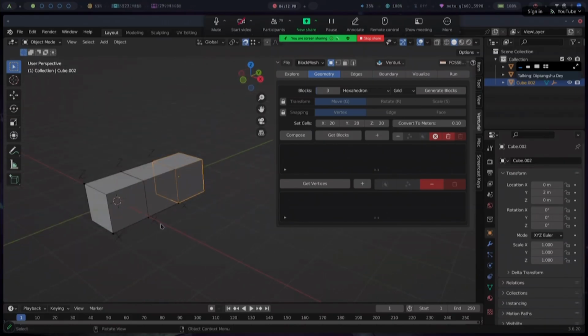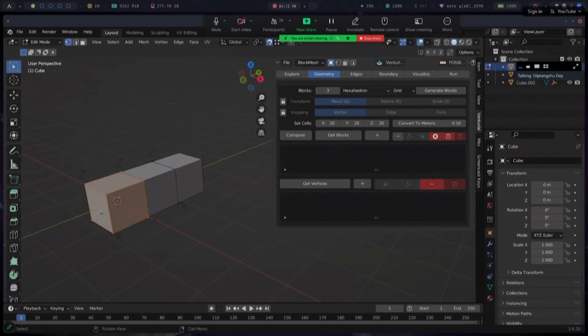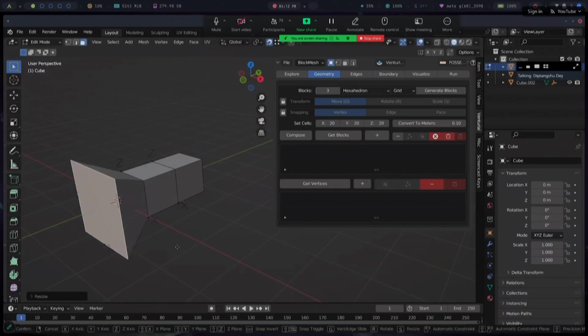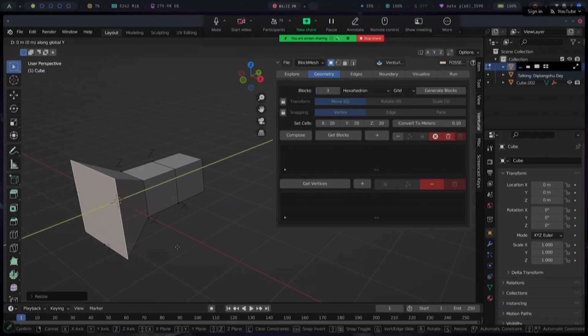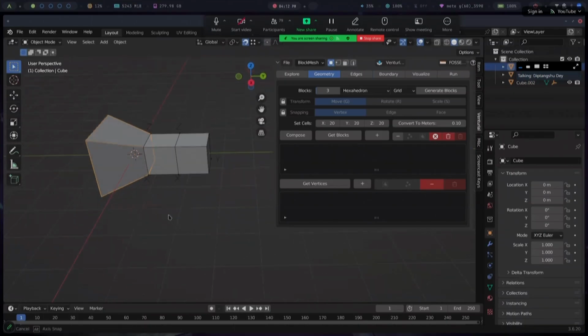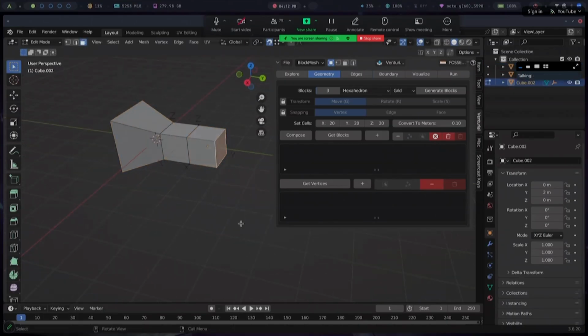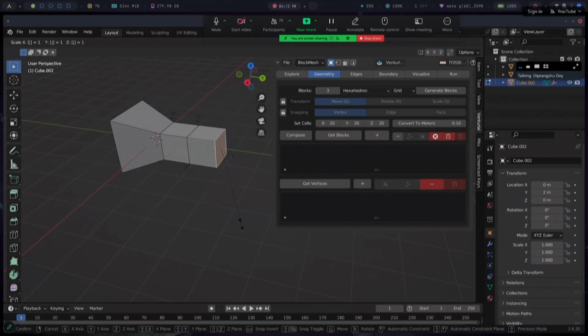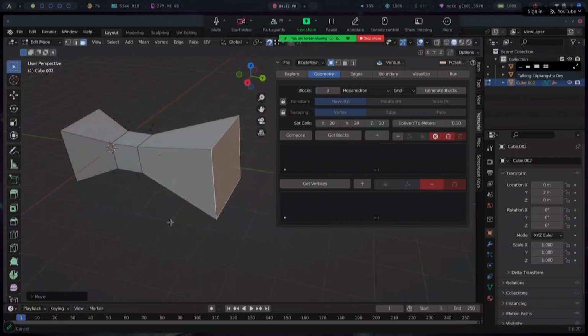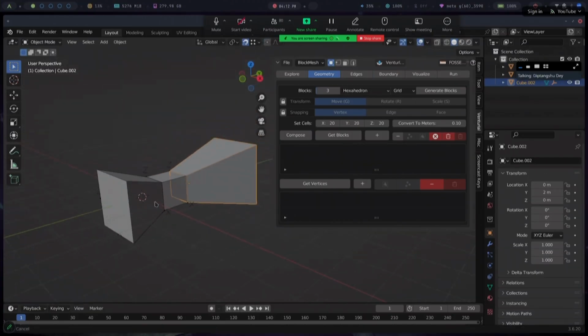And then once these blocks have been added to the viewport, I can modify their shapes however I like. So to make a Venturi tube, what I will do is I will just expand these to double this size, and let's drag it a bit backward. Okay. So this can be my inlet over here. And in this block, I will drag it, let's say 3 times, or maybe 2.5. And let's drag it outwards. Here. So here we have a shape of a basic Venturi tube.